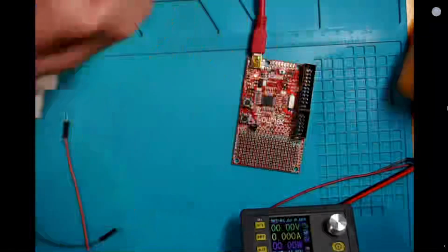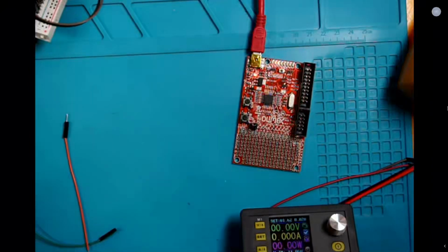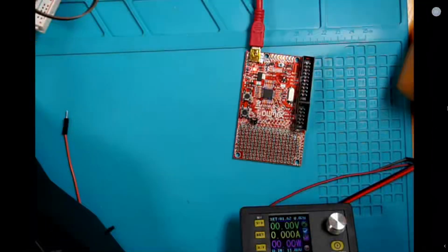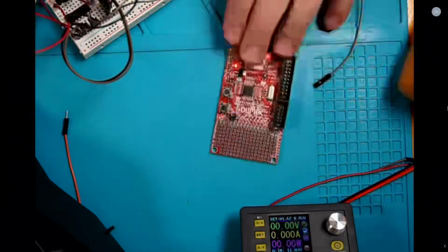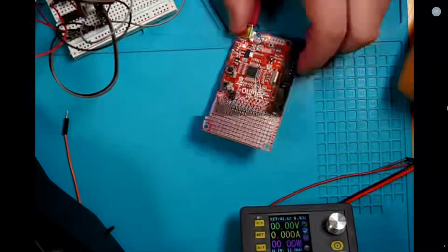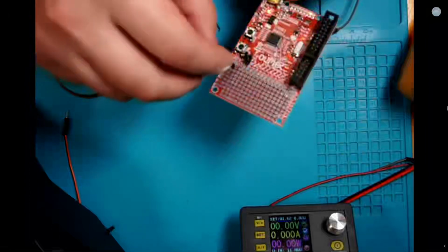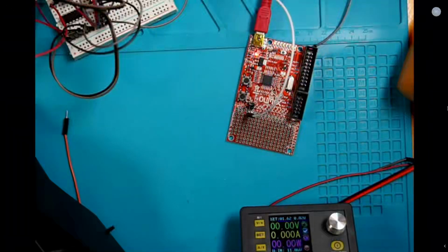So let's modify it. I'm going to grab my soldering iron, which is over here to the side. We'll just need one for this part. And I'm just going to add a connection. And we'll need a male to female wire for this. I'm just going to add a connection to the microcontroller right here. And this connection, like I said, is documented if you read the data sheet. It's going to be the 4th pin over here, the 2nd column over and the 4th pin. And this pin we need to connect to ground.